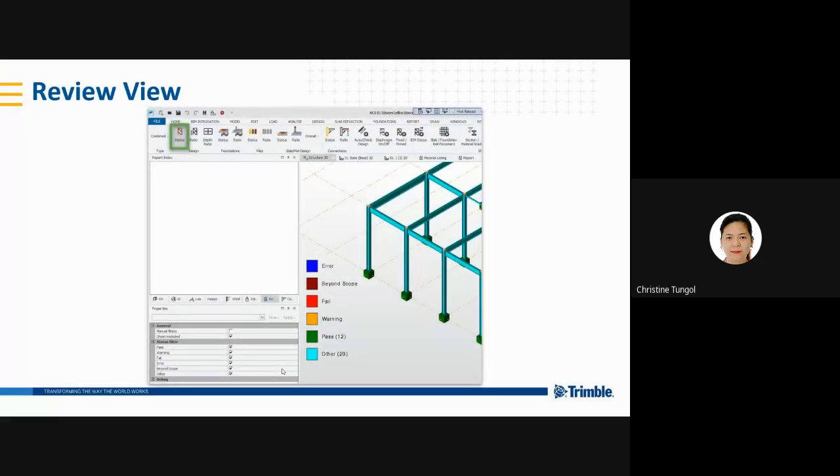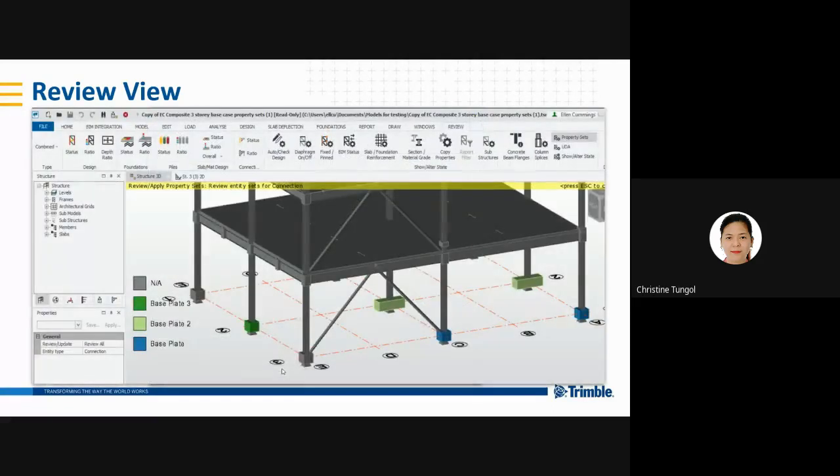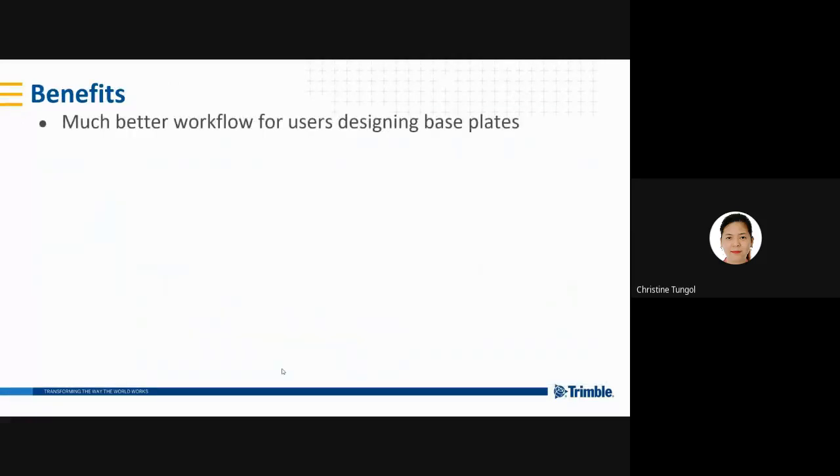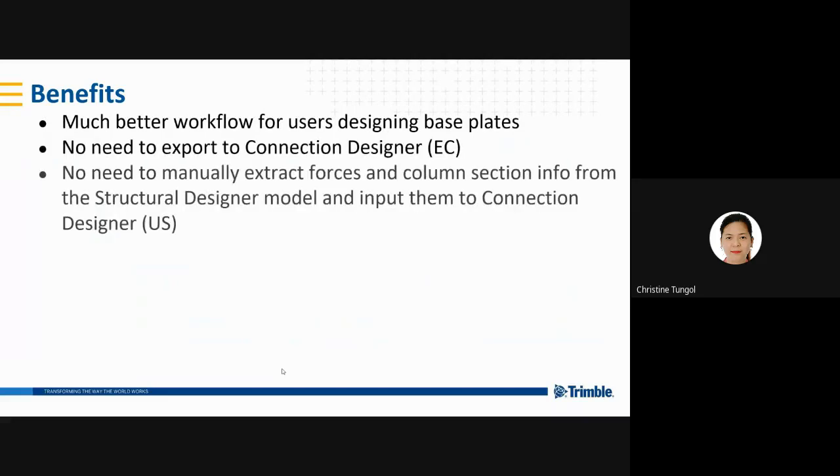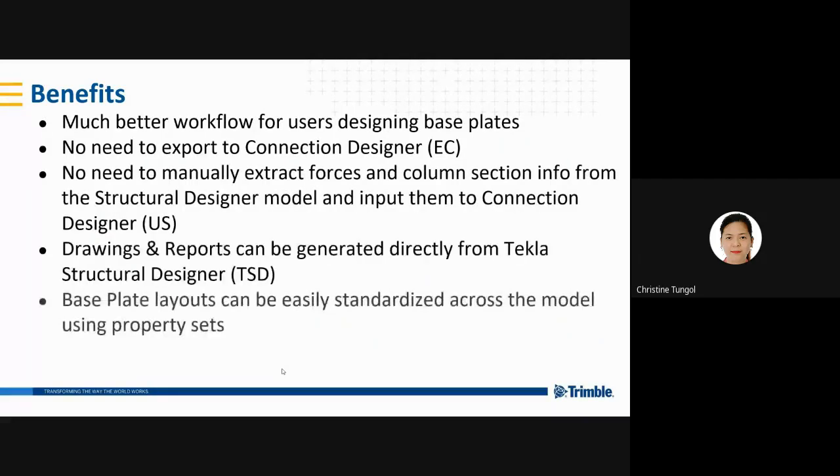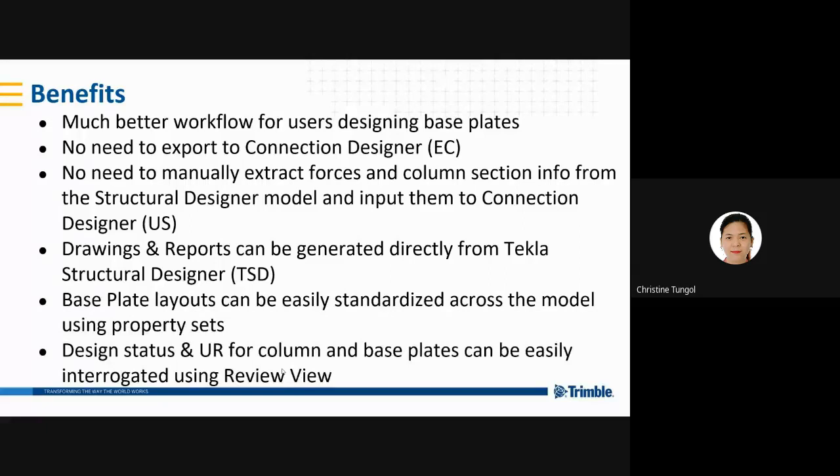So the status and utilization ratio can be viewed and will automatically open after the check all base plate is carried out. Base plates are included in the new review view filtering feature, and the property sets can be reviewed and applied using show alter state. So these are the benefits that you will have using the base plate enhancement in Tekla Structural Designer. So this is a good start for you.